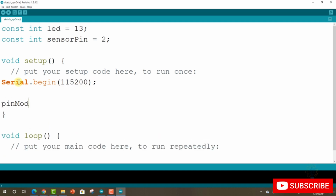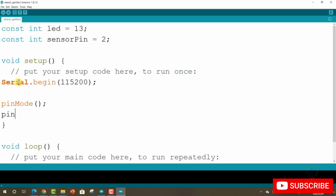Now the pin mode for the 2 pins that we are going to use, the LED and the sensor pin: we have to set the sensor pin as input, because we are going to receive the sensor data using Arduino, while the LED pin will be output.